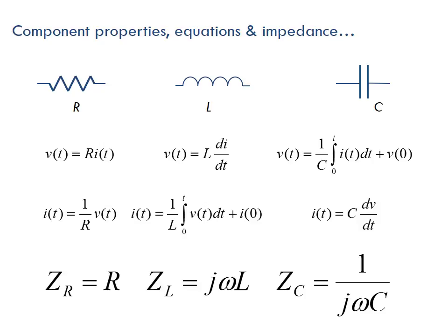You get the integral from 0 to t of v of t dt plus your initial current, whatever that was, I of 0. If you plug something in, your I0 is 0 because you just started. If it was already plugged in, then your I0 is some value, and you can add that in. So inductors are our integral circuit. Our resistors are essentially multiplying by a normal constant, like a slope circuit.